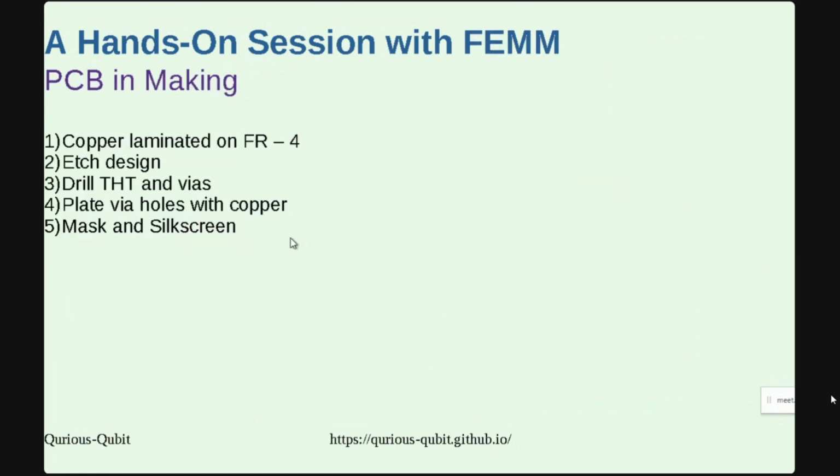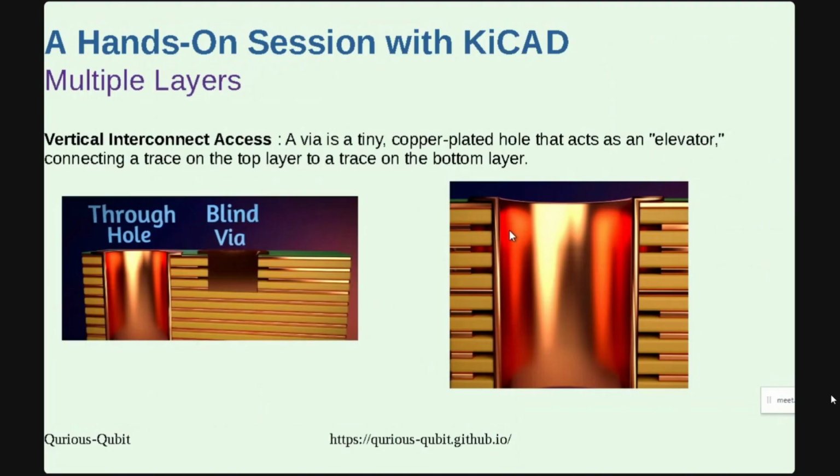And yeah, that was one thing. Another thing that I wanted to tell is, you may be wondering there are multiple layers, so there could be chances that this one hole could be conducting to different layers. That's avoided by having only one particular conducting layer. As you can see, this copper is only conducting maybe in level 5, it's conducting this to the through hole component. So other levels are insulated.